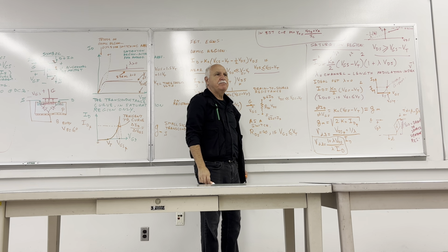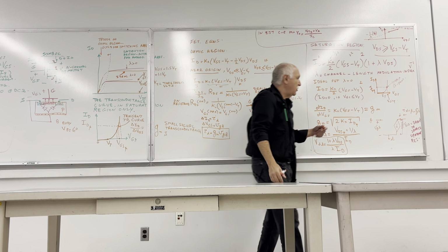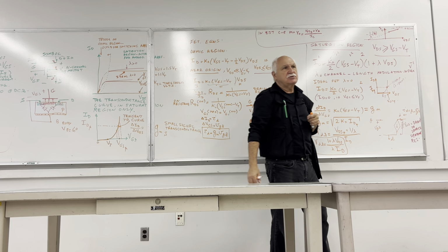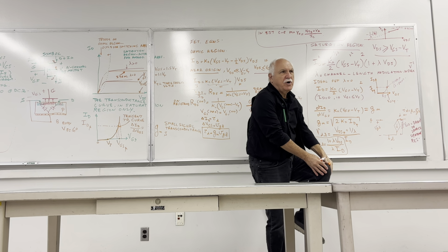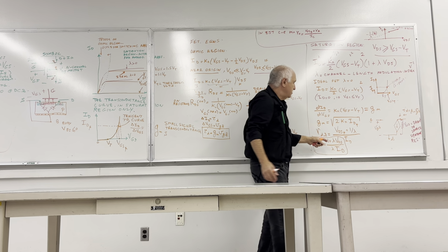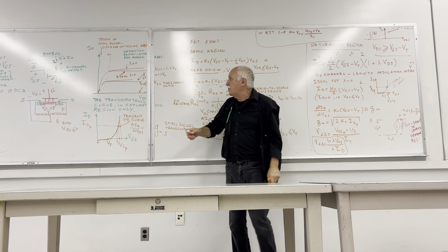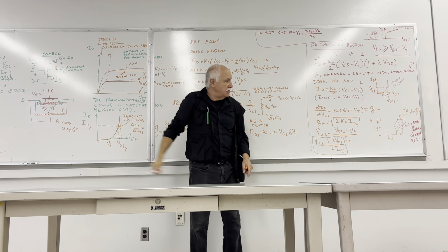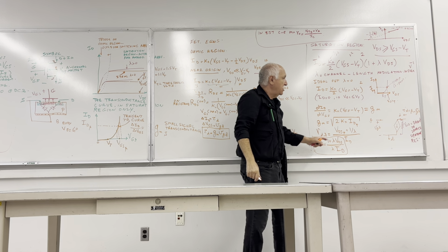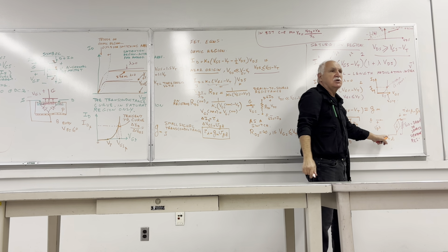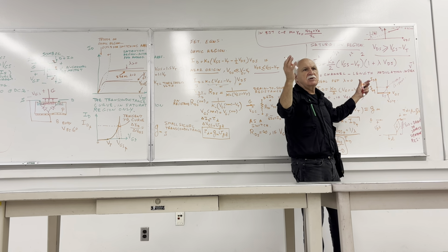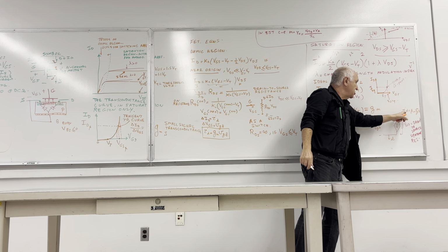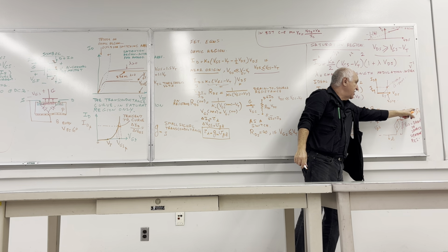That's what it is. So here is the situation. If you know the lambda for a transistor, yes, you can determine the dynamic resistance. No problem there. How do you do that? If you know the Q point where you're operating in the plane ID, VDS, and you know the lambda, stick it here, incorporate it in your small signal model between drain and the source. That's it.